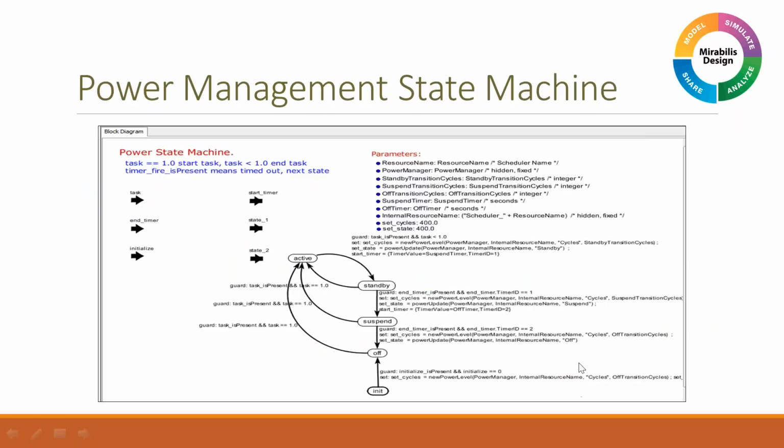You can also create complex state machines. The purpose for creating the state machines is to enable you to explore different power management algorithms. So for example, what do you do when your satellite is facing the sun versus when it's in an eclipse? Or for example, I'm now on auxiliary power. Which devices do I keep turned on? Which devices do I turn on?